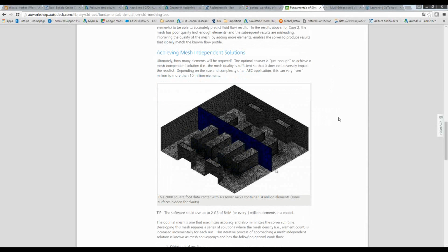What am I trying to say? Just to get the heat to transfer the way it would with conduction, because there isn't a solid there, you end up having to artificially bump up that heat transfer, and it's good to start with a simple test model. We used to do it a lot for characterizing heat sinks, where we'd do a little flow path over a heat sink and put a block that's a resistance.